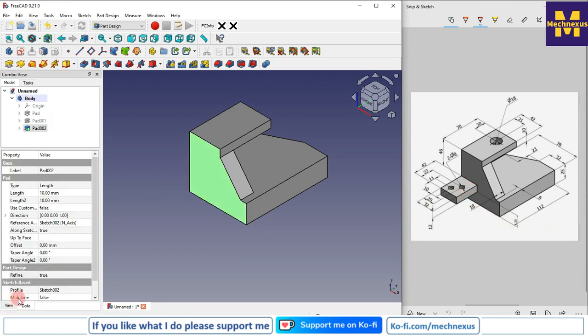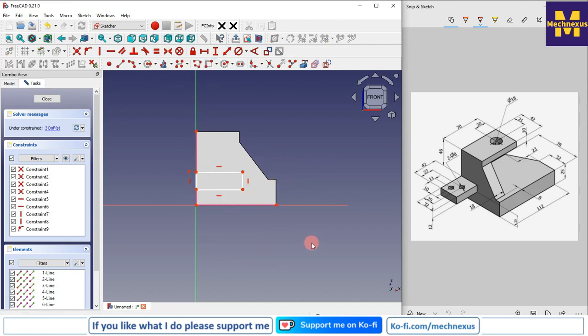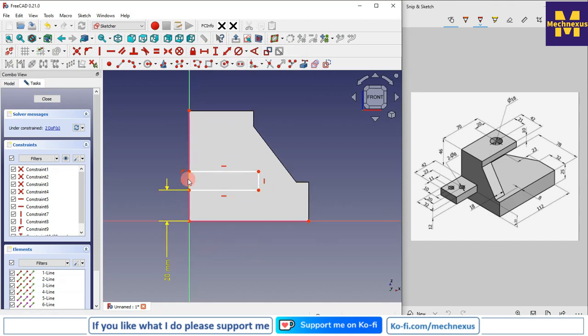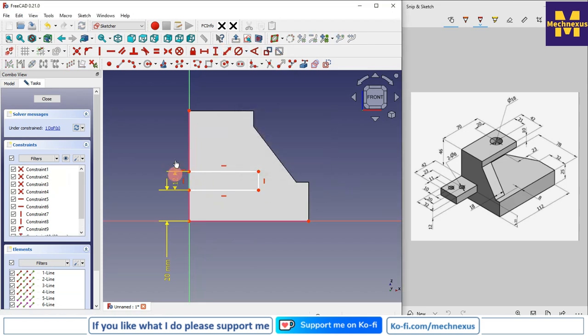For this we will select the face and click on the sketch, and we will project the geometry, this horizontal and vertical, and click on the rectangle, and now we will give the dimensions of 20 mm, and this is the 12 mm, 12, and this is the 32.